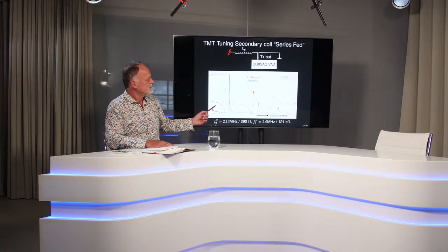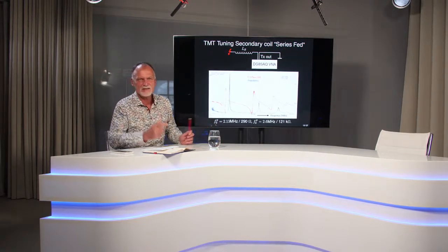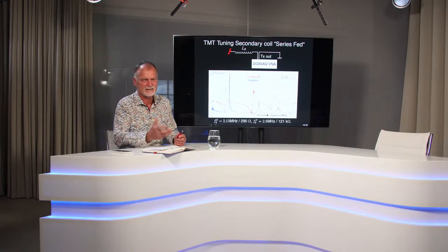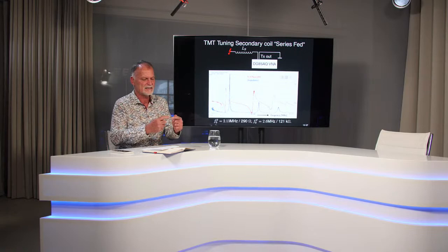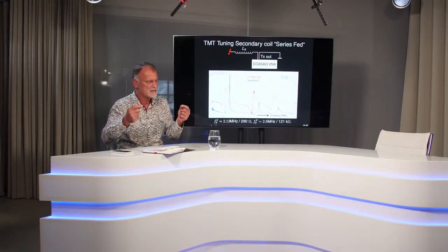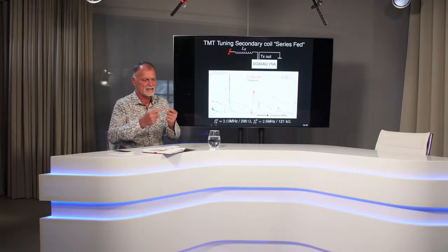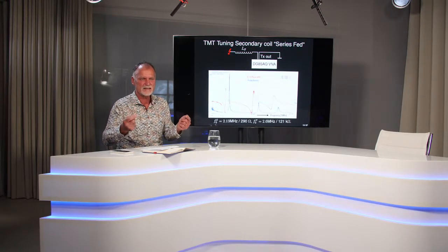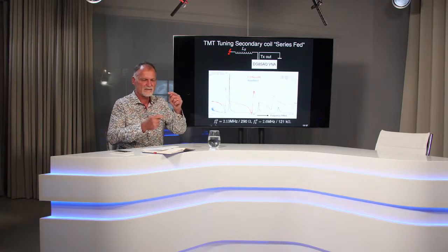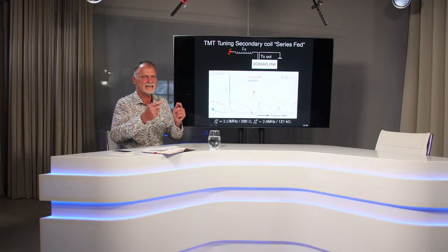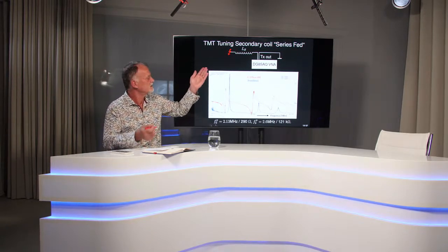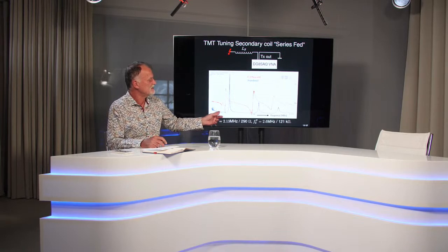Also there are two resonant modes. One is the serial mode, meaning your coil and the capacitors are in series, and in the resonance state the impedance of such a circuit goes to 0. Or you can have a parallel mode, when the LC are in parallel, and then the impedance goes to a very high value, kind of infinity. And that's exactly what we see here.